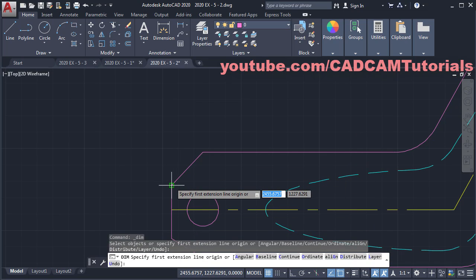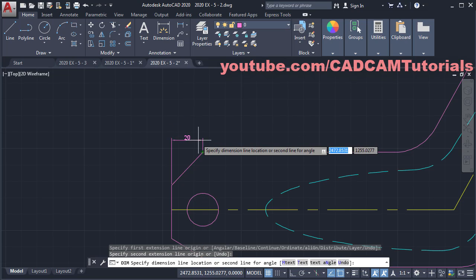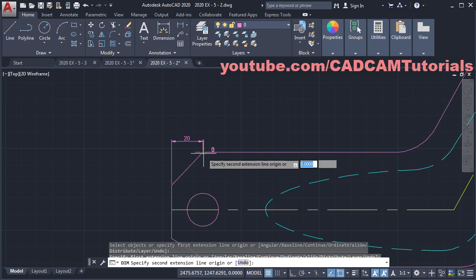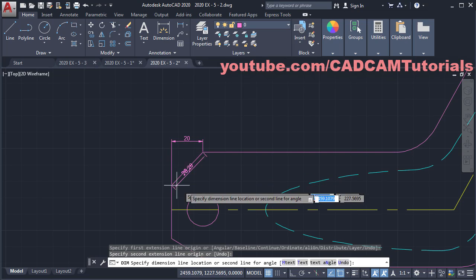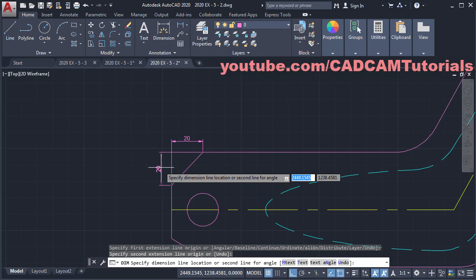Then click on this endpoint, click on this endpoint, then take your cursor above and click. Then click on this endpoint, again on this endpoint, take your cursor on this side. To force it to be vertical, make ortho on, then it will come vertical automatically. Click.